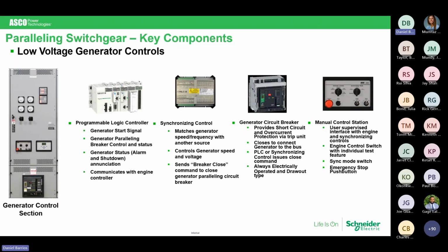The circuit breakers. When you look at paralleling switchgear in low voltage, you can either have that labeled as UL 891. Now, in UL 891, you can use fixed mounted breakers. You can use 489 breakers. Once you've gone into a UL 1558 type application, now each compartment is individually built so that you can't see between each of the cabinets.